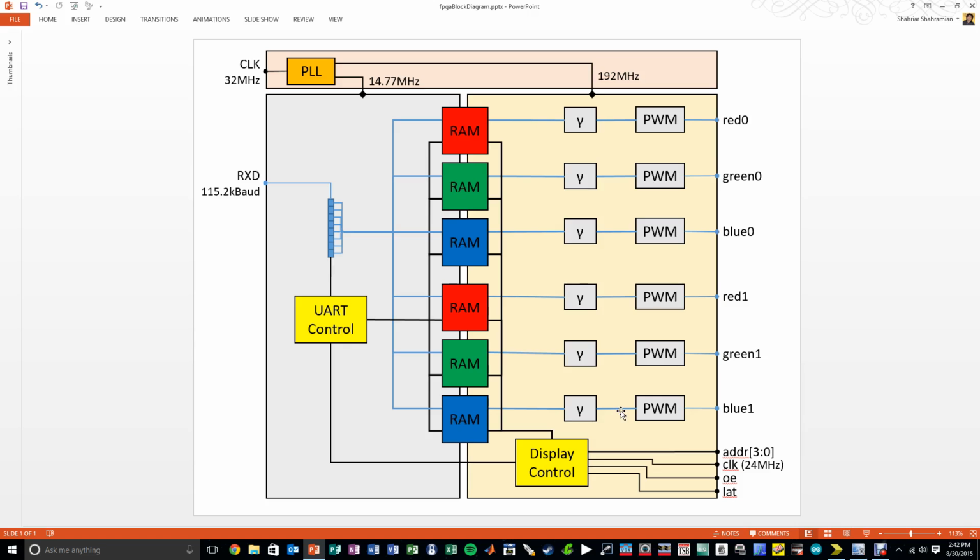And because you're doing that, you have full simulation capability of that hardware, because every bit of hardware that's inside the FPGA is fully modeled, and therefore you can completely simulate it. So I guess what we should be able to see is all of these red, green, blue, address, clock, and output enable, latch, the behavior, all of this through an entire frame can be simulated in an FPGA easily. Yeah, that's easy to simulate, and what is very nice is that actually all that software is provided